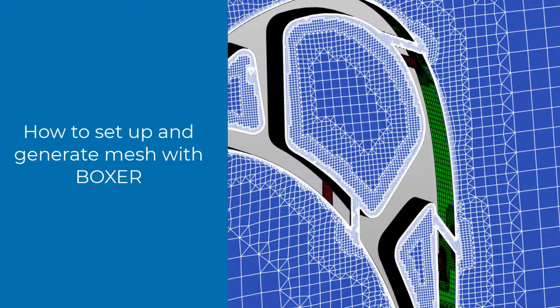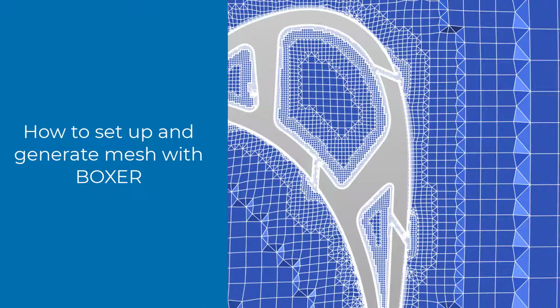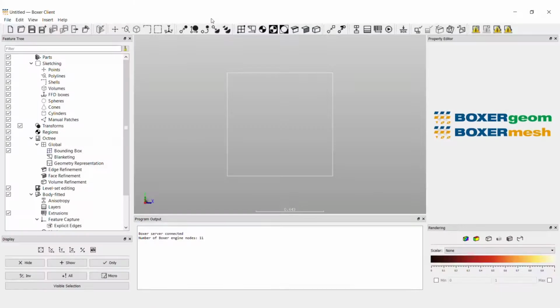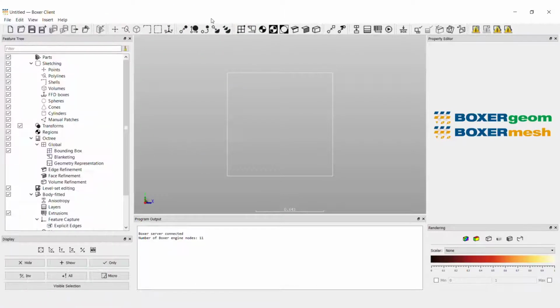In this video I'm going to show the workflow in setting up and generating a mesh using BOXER. I'm going to demonstrate how to produce a mesh for a cooled turbine blade geometry to show the workflow. The first step is to import your geometry. BOXER can import a wide range of CAD formats, and you can combine multiple geometries from different formats in BOXER.